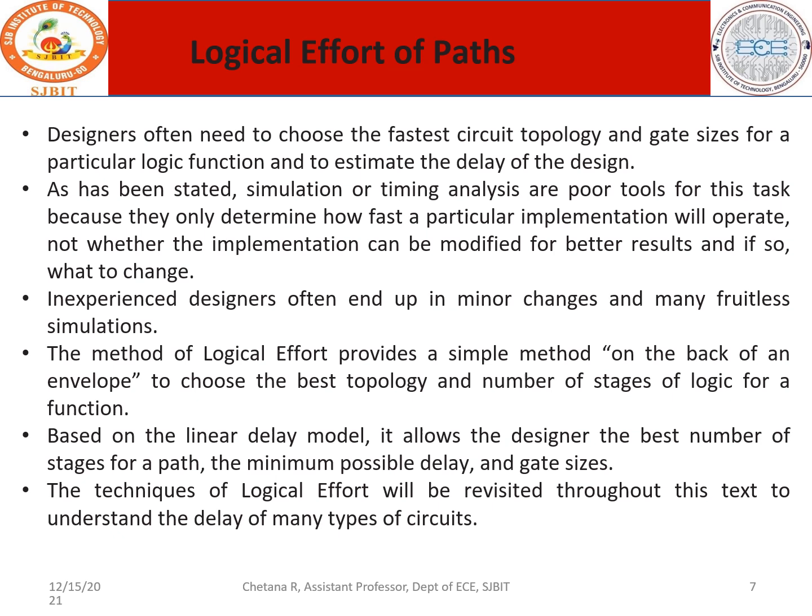So what exactly does logical effort mean? It provides a simple method, on the back of an envelope, to choose the best topology and the number of stages of logic for a function. So the purpose of logical effort of paths is to choose the best circuit design topology, and also tells us how many stages of logic should be considered.